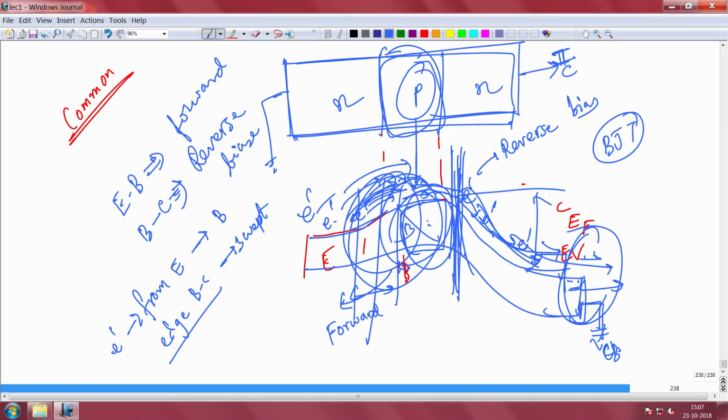And we have introduced the concept of the BJT as 2 back-to-back PN junctions, one of them forward biased, one of them reverse biased. The idea is that the forward bias junction will inject electrons that will diffuse across the base, some of them will recombine there in the base because the base is p type doped, and some of them will reach the edge of the collector depletion. As soon as they reach the edge of the depletion, they will be swept away. So, this is the basic functioning of a BJT.